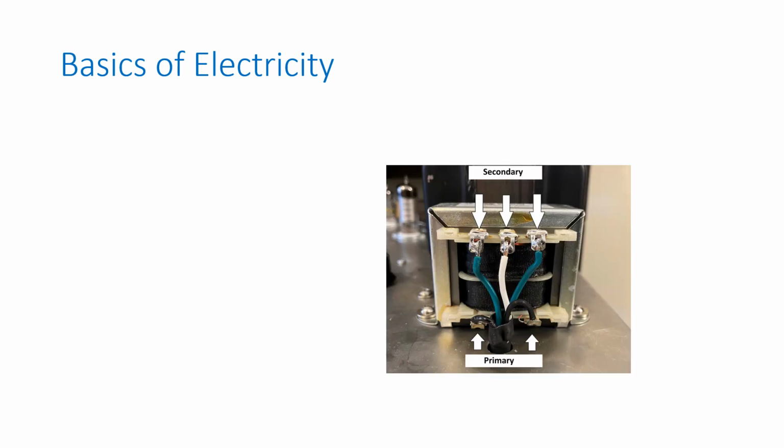In this example, the primary are those two black wires soldered to those two lugs at the bottom. The secondary are the three wires at the top. There's a center tap on the secondary. You don't really have to pay attention to that white wire in that middle terminal. You can pretend it's not there. Notice the windings are wrapped around the same core in the middle, and notice the core is just like my little H-frame diagram. There's laminations all the way around, hidden under that chrome or steel frame. Like I told you, that really is how transformers are built.